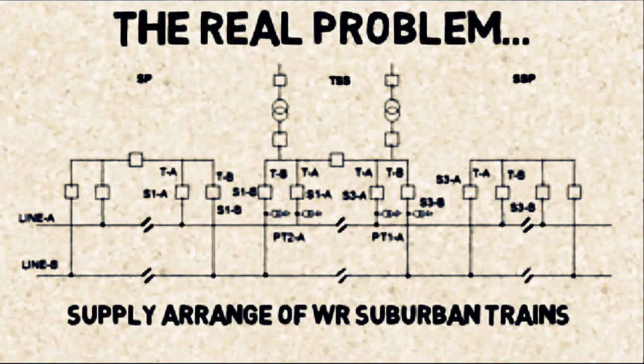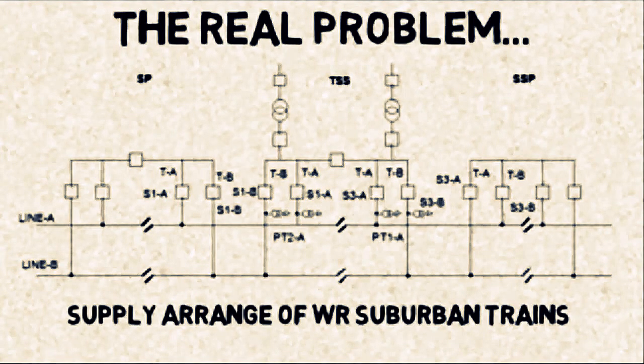For the successful operation of the panto flashover relay, it is necessary to monitor the status of both the circuit breakers and control the remotely located circuit breaker. In the present condition, it is not practicable to provide direct cabling between the remote circuit breaker and the location where the panto flashover relay is installed.